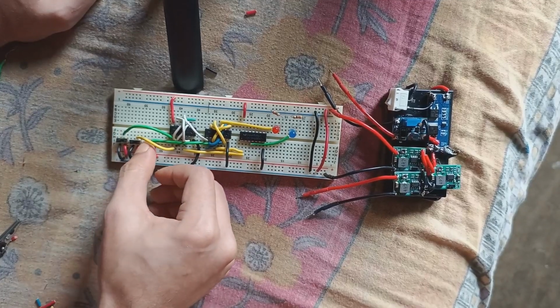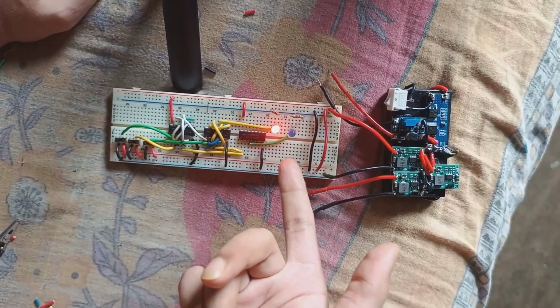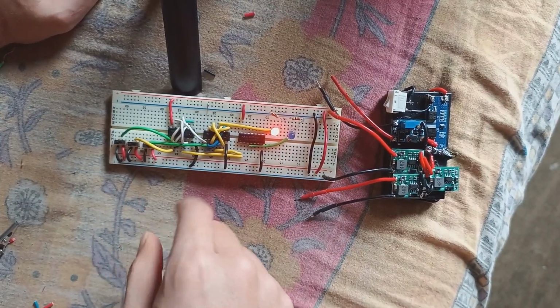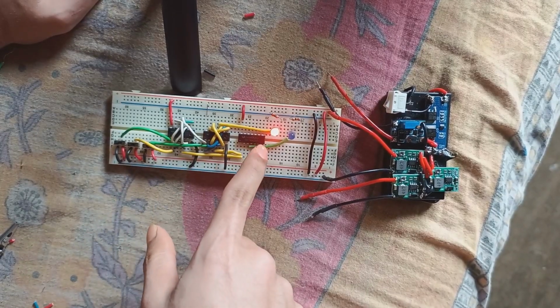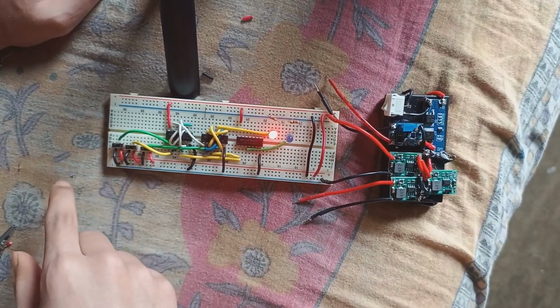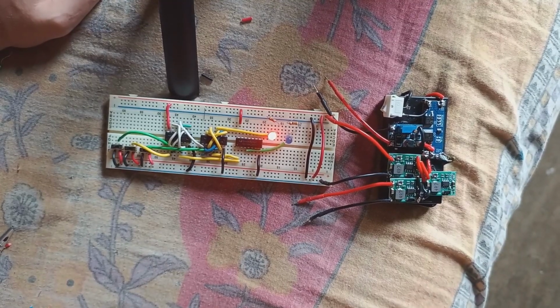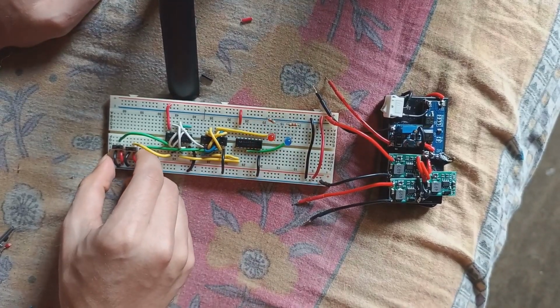And now for the carry. Now carry is 1 and both variables are 0. Sum is 1 and carry is 0 at the output. This is the carry in, this is the carry out. In this scenario where the carry in is 1, the sum is 1 and carry out is 0 because the other variables are 0. In simple binary addition, 1 plus 0 plus 0 is always going to be 1, nothing extra, not any carry. Okay, that covers a single 1.